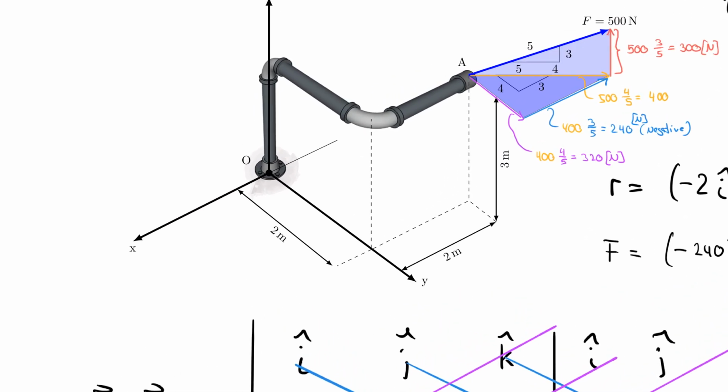So let me pull out my ruler here and draw the first moment, which, remember, was negative 360, right? Negative 360 means nothing else than a rotation in the negative direction. So this here was 360. And please note that I used a positive number here because the direction shows negative. So we will never draw negative values in a sketch. We only draw positive values in a sketch. And here I drew it with 360 in that direction.